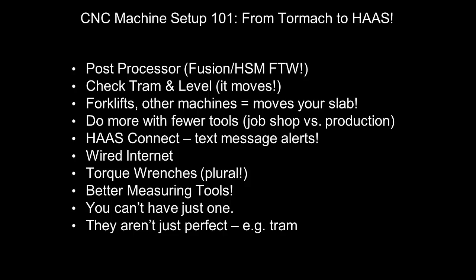So now what I've done is we're using dedicated torque wrenches on the 3/4 inch for the vise itself, for the cap screws that secure things down, and we're getting much more consistent parts because every time we touch a fastener on the machine, vice screw or anything, it's torqued consistently.